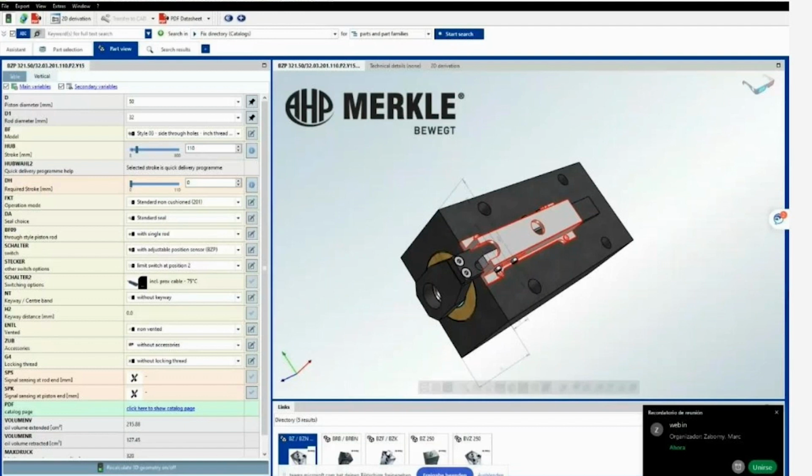Great. What are the pressure ratings in comparison to tie rod cylinders? Okay. We have the tests that we made with the tie rods. We recommend our customers only go up to 160 bar. We know that Parker points out that they can go up to 210 bar.